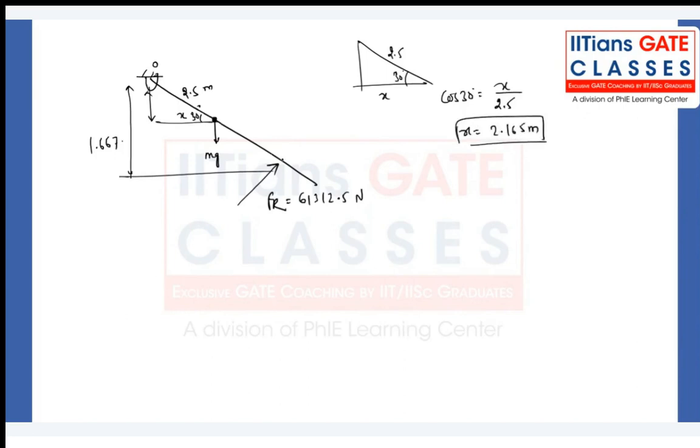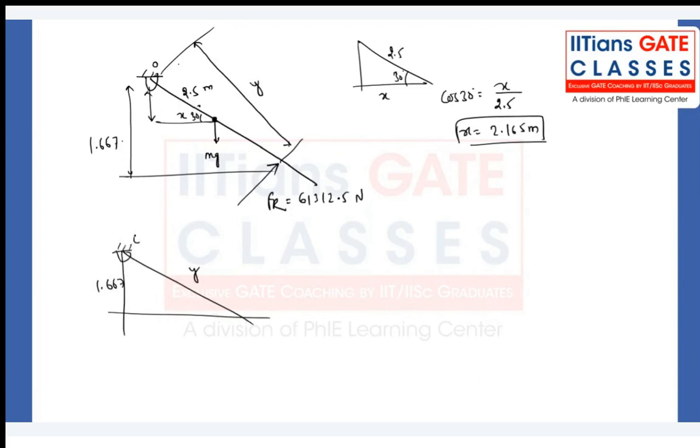And what about this particular distance? Because we have to take the moment of the hydrostatic forces, right? Let's say this is y. So from a triangle, we can calculate: this is y, this is 1.667, and this particular angle will be 30 degree. Then what we can write? Sine 30 degree will be 1.667 divided by y. So y will be 3.334.